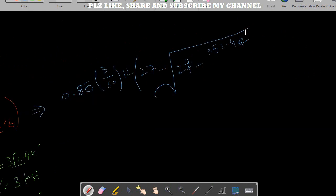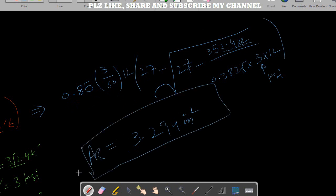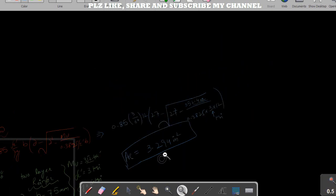So let me plug in all the values. We have to multiply it with 12 divided by 0.3825 multiplied by fc prime, which is 3 ksi, into 12. Here I am using ksi, and because I am using kip-inches, the units must be consistent. Now we can plug all these values in the calculator and we got 3.294 square inches, which is my desired area of steel. So this is from this equation, right?